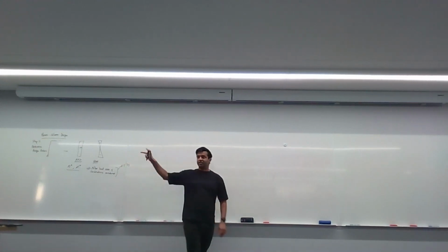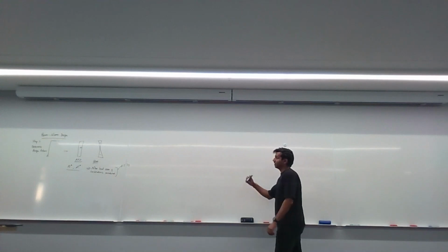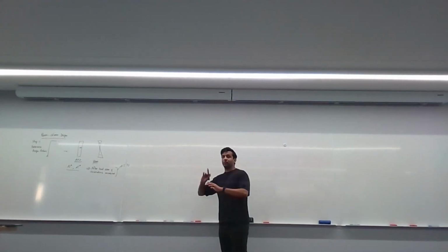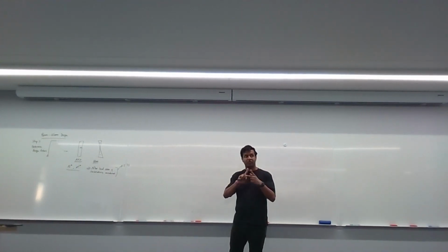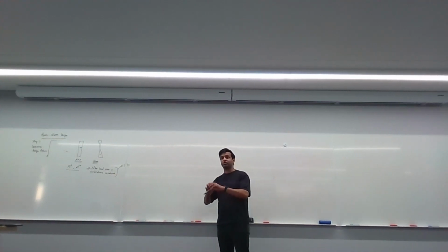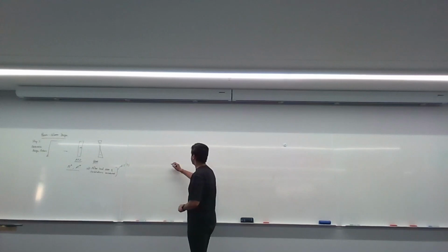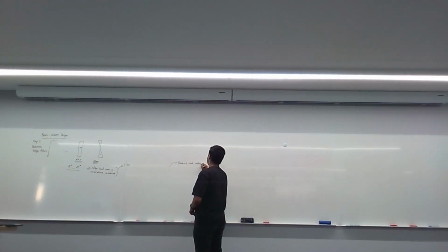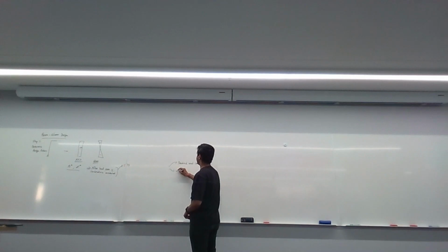Okay, even though the design is all according to AS 4100. Now, just remember, when it comes to wind, there are two important load cases we need to consider. Not the only two, but the two that are specific for wind. You have your standard wind case, standard wind condition, and then you have wind action reversal.